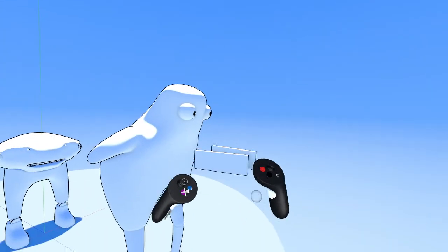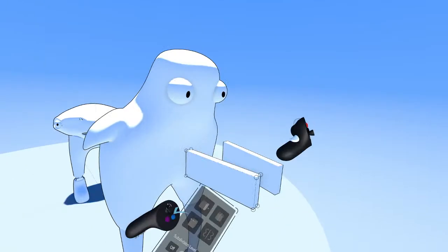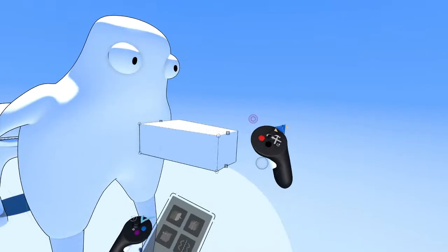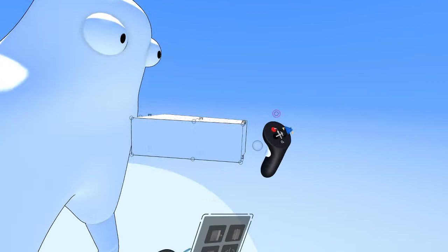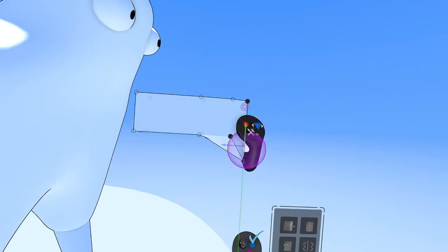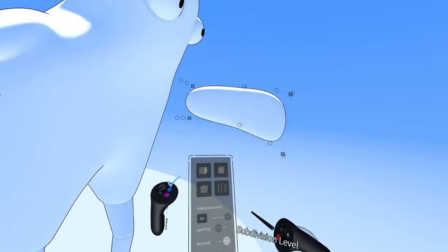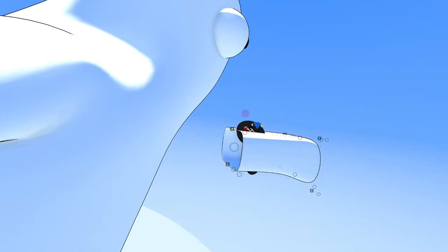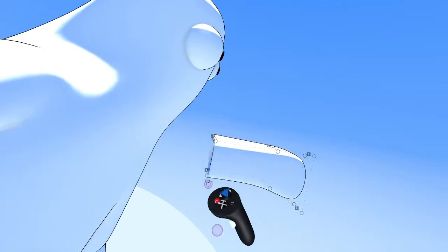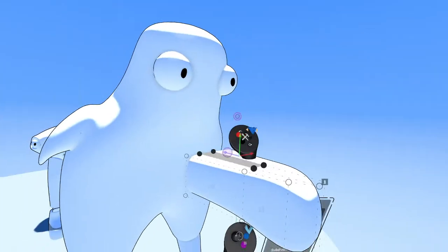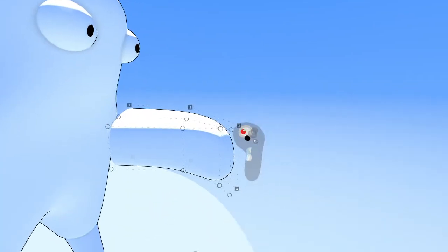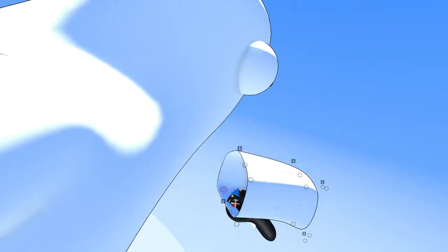All right, now let's make the beak. Again, convert to sub-D. Let's drag that face to the mirror plane. Let's turn on subdivision and delete these faces. You delete the faces at the end of an object if you want a clean transition and you don't want it to subdivide at the very end there. In the case of the beak, we're just going to intersect it with the face here, so I don't really need a closed-off face back here.